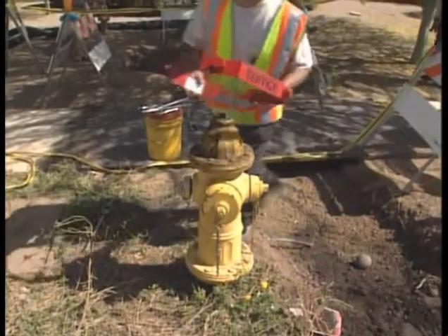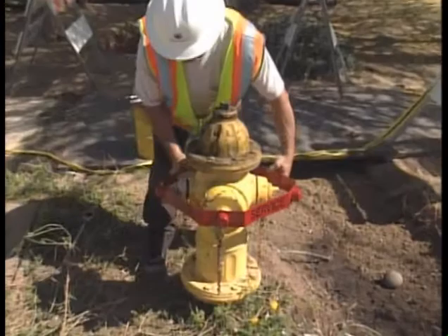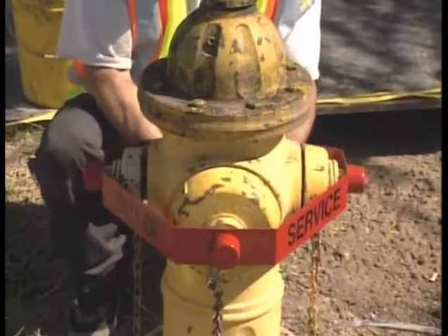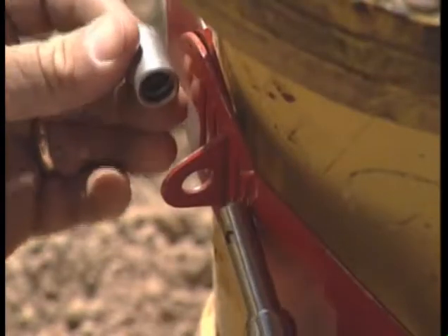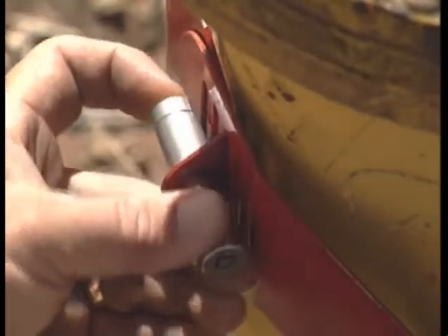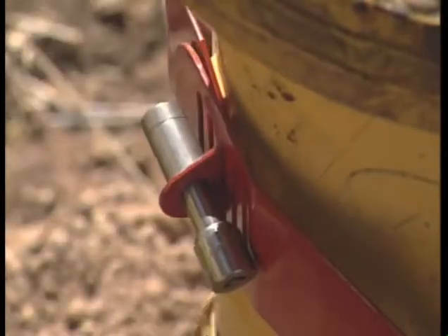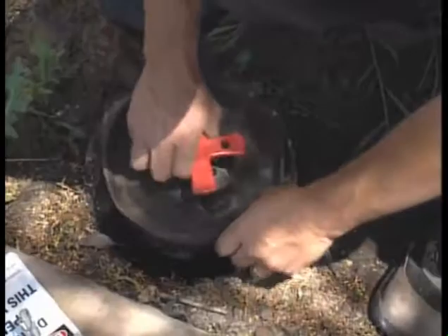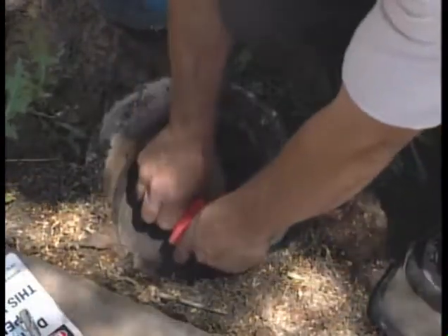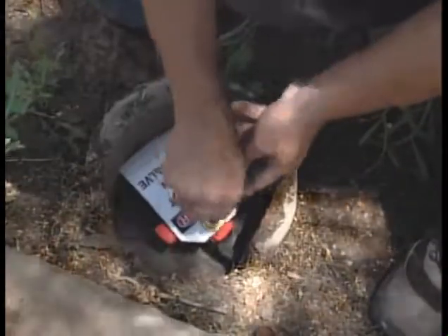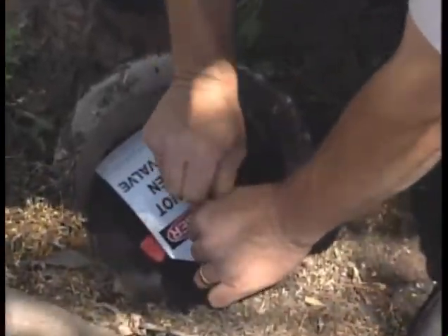Lockout tagout is exactly what it implies. It's the process of using equipment that will physically prevent the energy source from being used. The flow of water in this case. Moving parts or the on and off controls are locked into place. But that's not enough. To prevent someone from removing the lock, it's also necessary to use a tag with information alerting other workers to the fact the energy source has been shut off and should remain off.